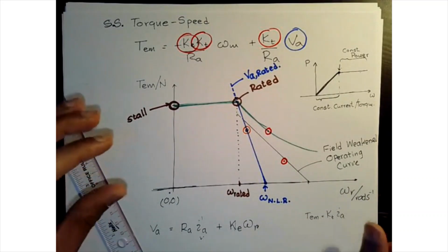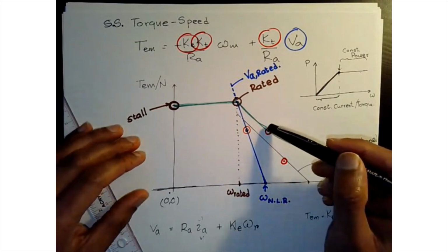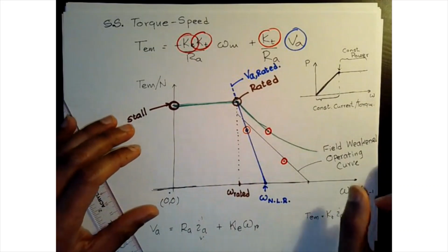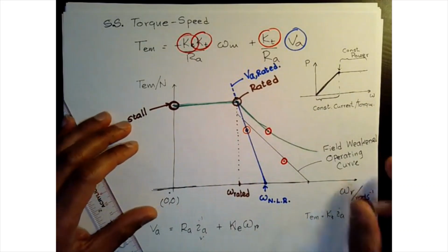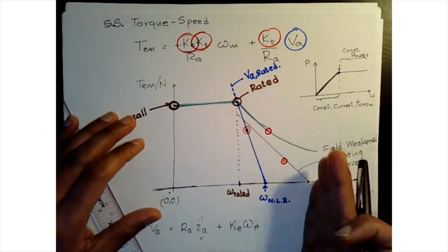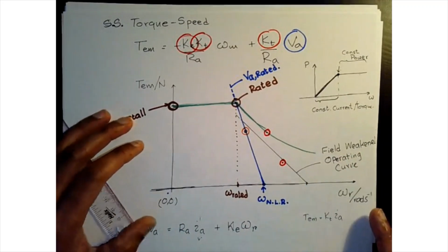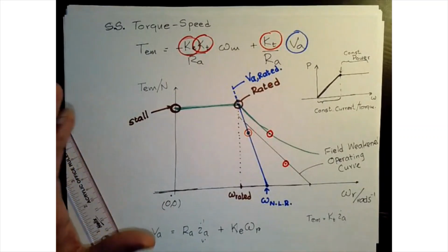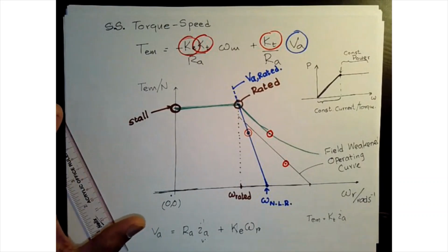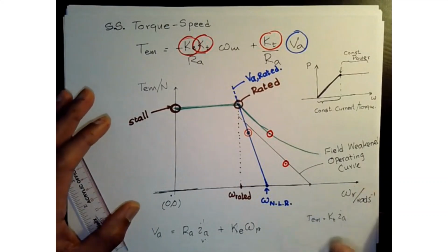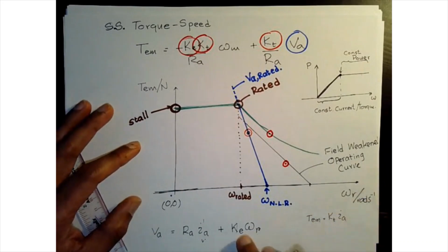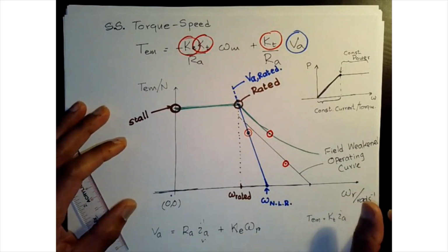If you want to reach higher speeds and not deliver the same amount of torque, you're now at the peak power capability of your power supplies, and you're optimally using them to go to a higher speed without changing the machine design. You're influencing Ke. I don't think that's considered changing machine design. It's kind of having a variable to control to get to those higher speeds.